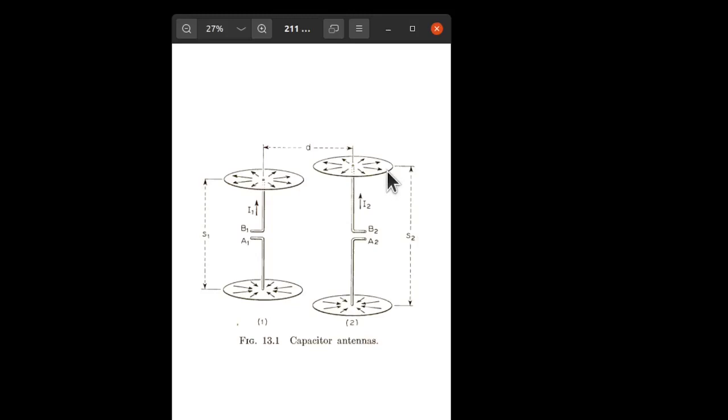But it is a way of shortening the dipole, maintaining its launch characteristics, and maintaining its efficiency by ensuring that I2 or I1, the current in this branch, is sufficiently large enough to connect to the radiation resistance, which is still on the order of the standard dipole, or about 140 ohms.